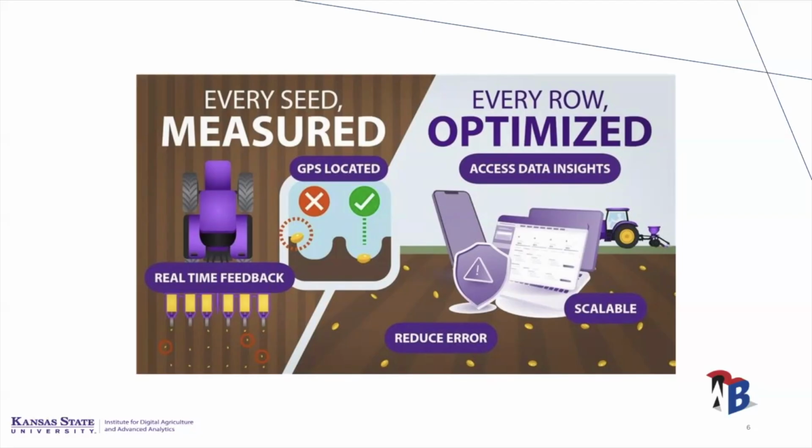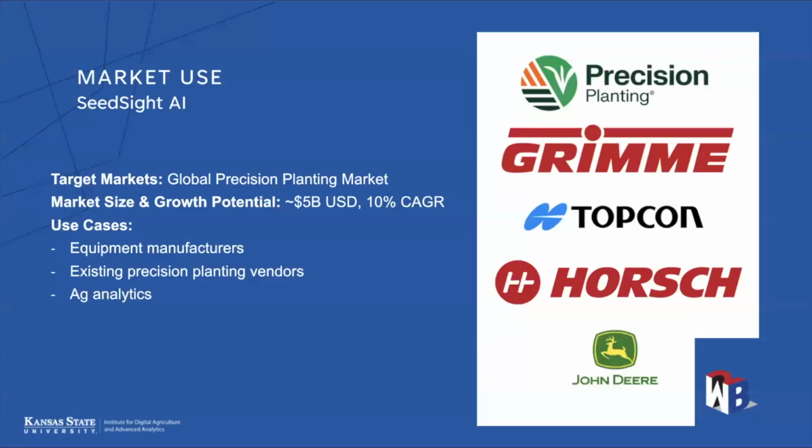You will know if you are leaving large gaps, if your planter can adjust its downforces to have continuous accurate depths, and if you want to adjust your vacuum and other things to make sure your seed singulation stays on par. You will also know if you are not planting seeds because of certain blockages. But the bigger thing I want to say is that we really want to optimize every single seed in a row if you want to maximize the yield on a per acre basis, row by row.